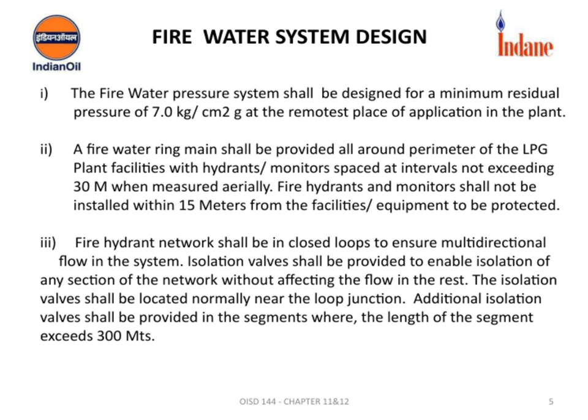It's important to note that fire hydrants and monitors should not be placed within 15 meters of the facilities or equipment they are meant to protect. This distance helps prevent potential damage to the firefighting equipment and ensures safety during operation.